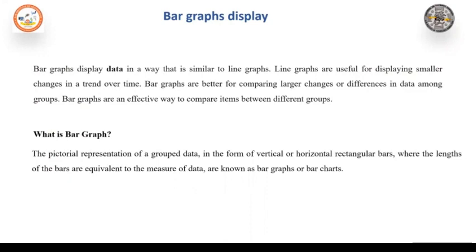The LED bar graph consists of a number of LED arrays arranged in a single or multiple column. The packed density may be as much as 50 to 200 devices per centimeter cube, and the display size can be as large as 50 mm by 100 mm.